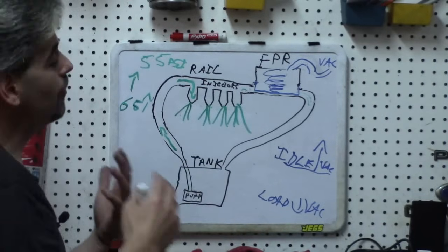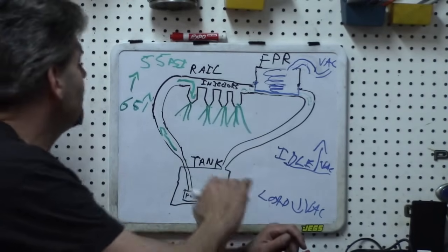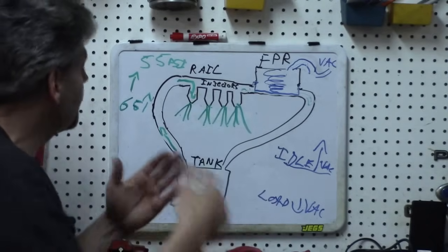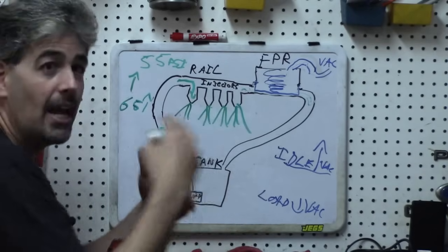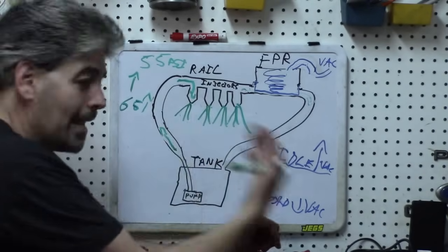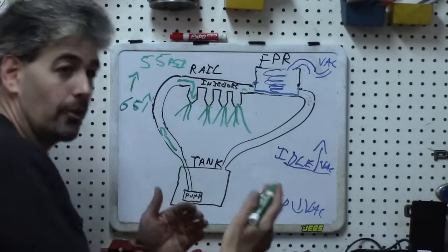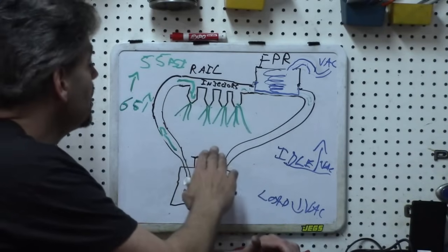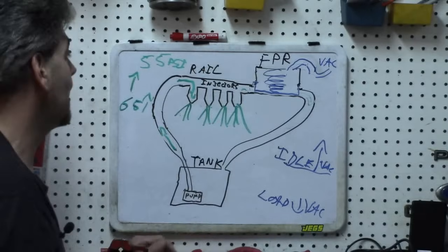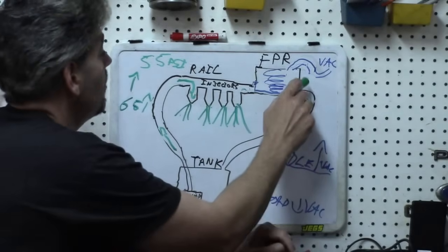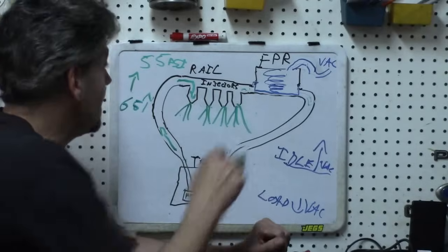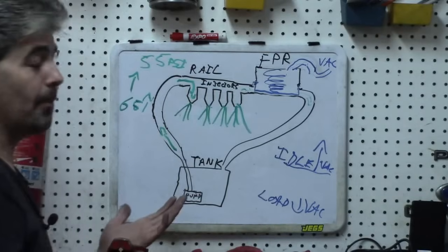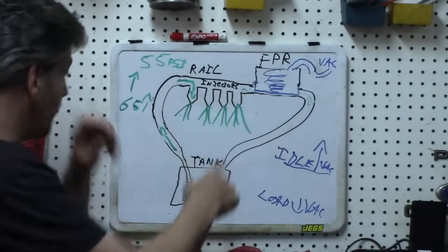Now, most of you guys who are experts in fuel trim realize that that rich condition is going to be compensated for when detected by the O2 sensor, so the pulse length will be adjusted so that we get a better air-fuel mix, and the short-term fuel trim will eventually level off. But the long-term fuel trim is still going to show that rich condition, and almost certainly you would throw a check engine light in this condition. So you would look and see if you have a vacuum leak in the hose as maybe one of your first steps. What's another very simple way that you could validate this as being the issue?